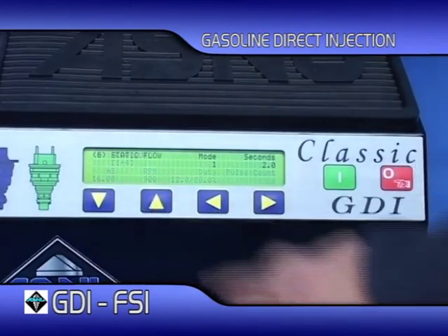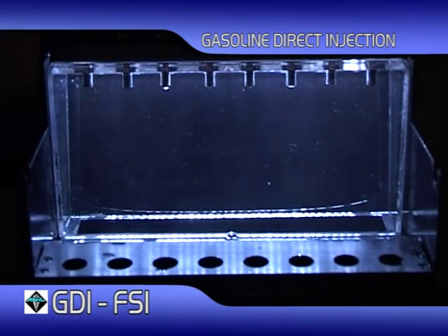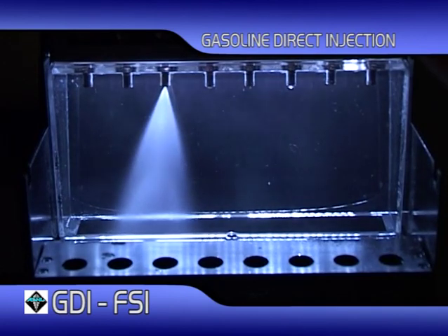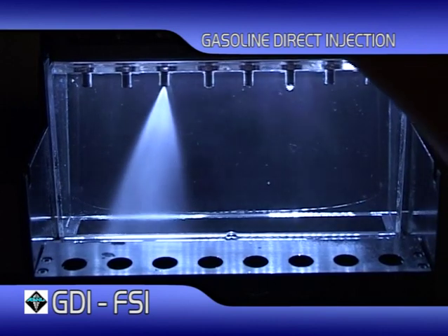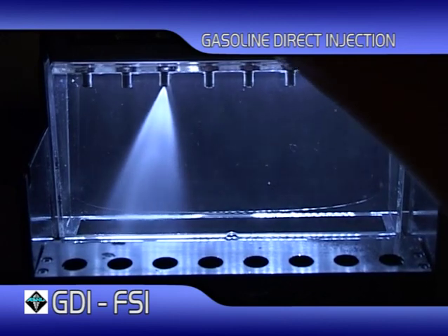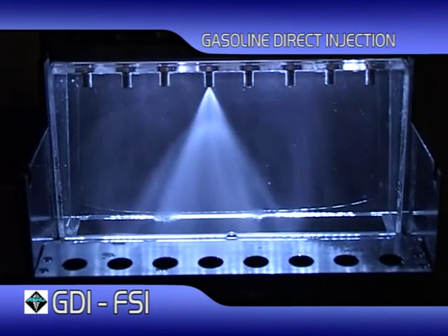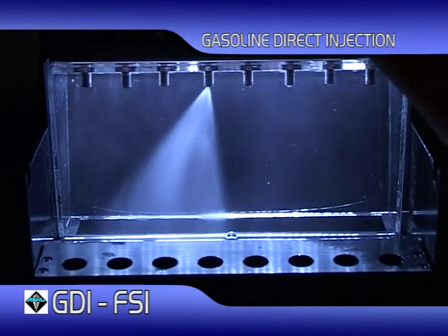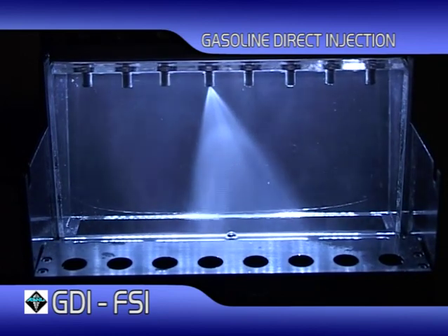We have now selected the static flow mode. This will run the injectors in wide open mode. This will enable the user to check the static deliveries of the injectors and compare the results against the dynamic deliveries. This highlights an issue that may be related to the electronic operation of the injector. It is also a good opportunity to visually see exactly what shape the spray should be. By rotating the injectors during this mode, you can determine if all the injectors are spraying at the same shape and angle.